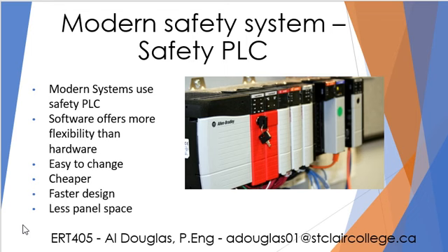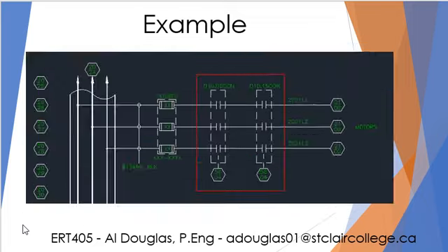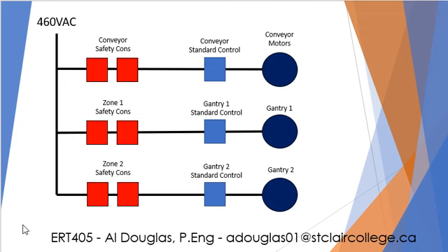Your safety PLC is probably going to be red, and we are probably going to control actual contactors which will physically interrupt the high voltage power going to motors or robots or other devices like that. So we have standard logic that controls our regular contactors, and then we'd have safety rated contactors which we will use in pairs. We always control outputs in pairs.